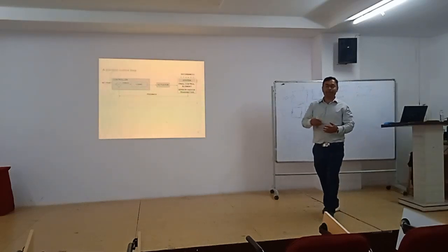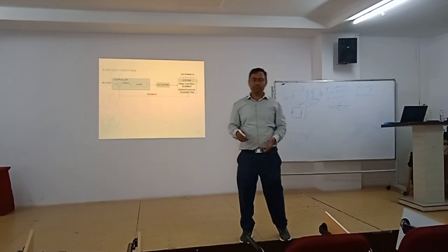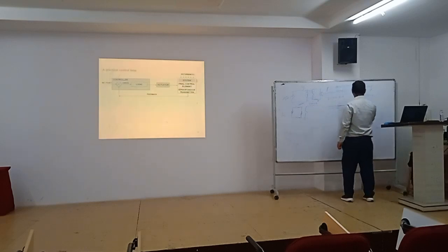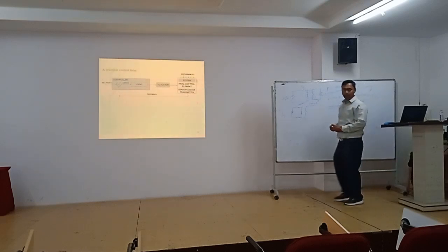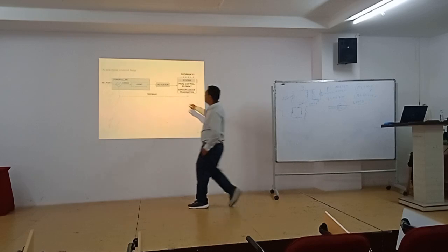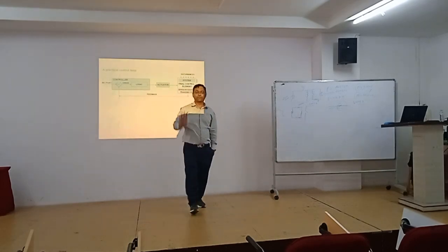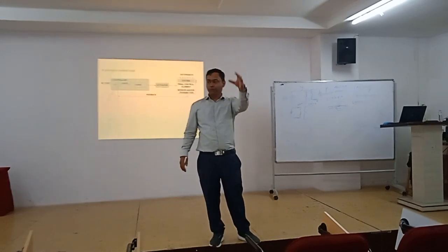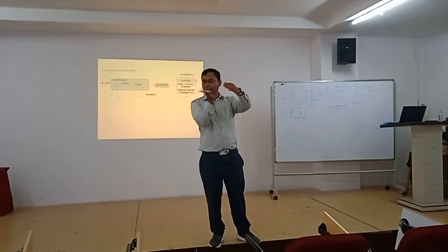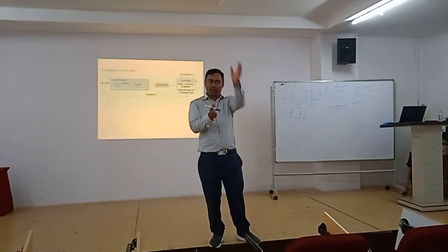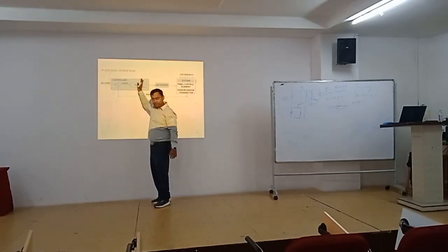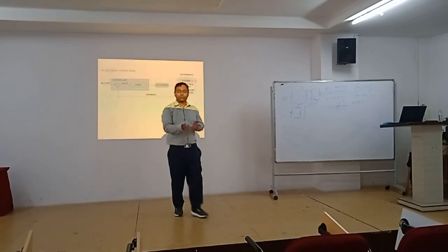So now we have to control the speed of the induction motor. One of the good options is you can go with a VFD. So as an actuator here, we have gone for the VFD. Correct? You are measuring the flow. If the flow is not as per your requirement, then you need to increase or decrease the speed. That calculation we are doing in the program, in the PLC, and based on that calculation we are increasing or decreasing the speed through the VFD.